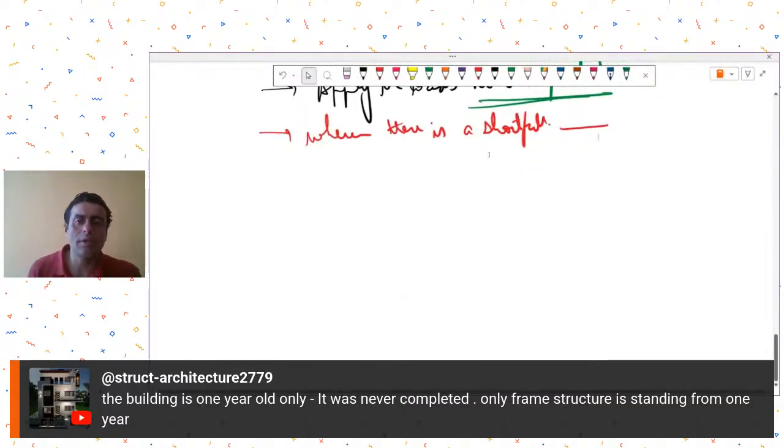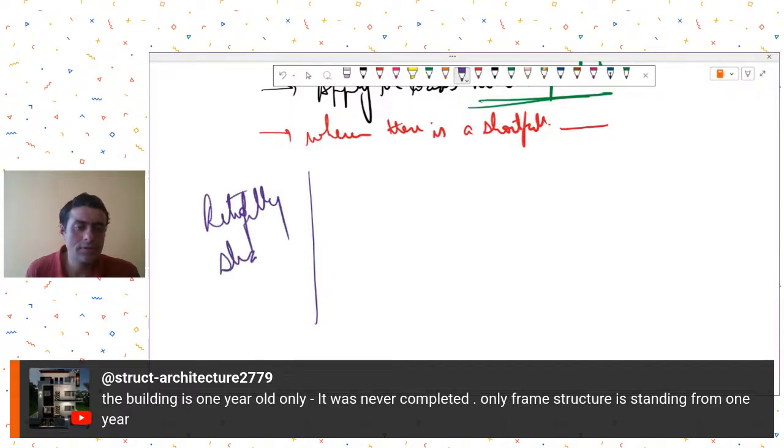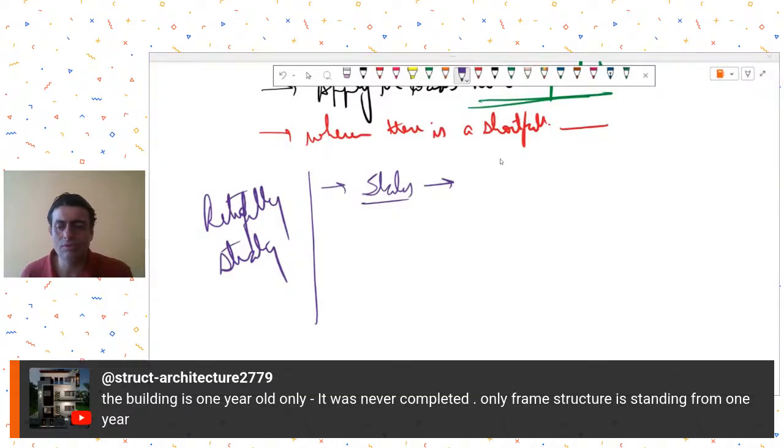So now what can be the retrofitting strategies? Retrofitting strategies for slabs. Now for slabs, it is slightly tricky. Retrofitting strategy for slabs will be slightly tricky because if reinforcement is insufficient, in my opinion, slab reinforcement will come out to be okay, because even if you are providing, let's say, 10 at 150 both ways, it is more than sufficient to take large amounts of live load. So I think slabs will be okay for you.